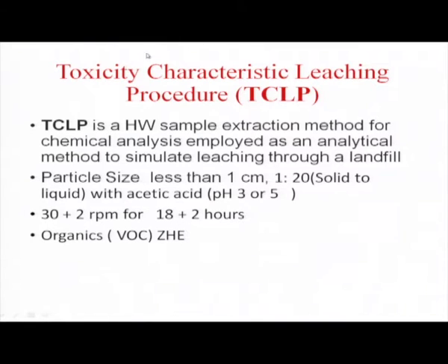Usually the TCLP test is a laboratory based test. It has to be conducted with the help of appropriate instruments. The TCLP test on a hazardous waste sample involves an extraction method for chemical analysis. After the extraction, it is subjected to analytical determination of a particular pollutant, and this test actually simulates leaching through a landfill.